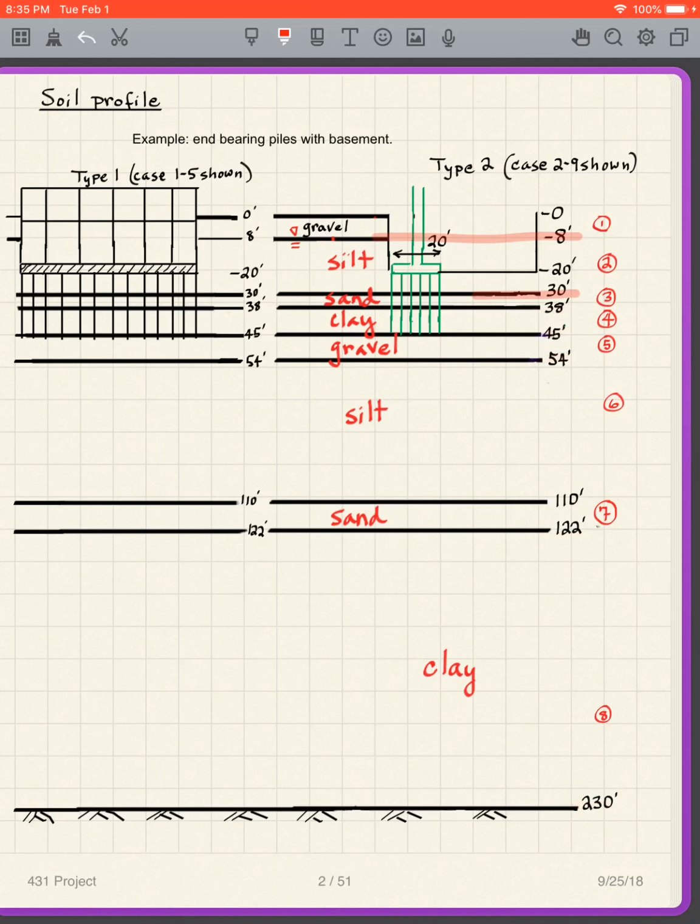If you look at this, what do I have? I've got the trouble areas, of course, of the silt layer, that clay, silt, and clay. And between those layers, there's a thin layer of sand there. There's some gravel on the top. There's a little bit thicker layer of gravel there. A little bit thicker layer of sand there. So a lot of silt and clay, and interspersed, I have some thinner gravels and sands.